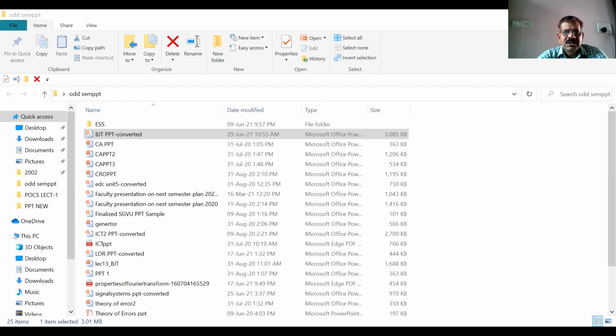The base is much thinner than the other regions. The emitter is heavily doped so it can inject a large amount of carriers into the base. The base is lightly doped so it can pass most of the carriers to the collector. The collector is moderately doped.